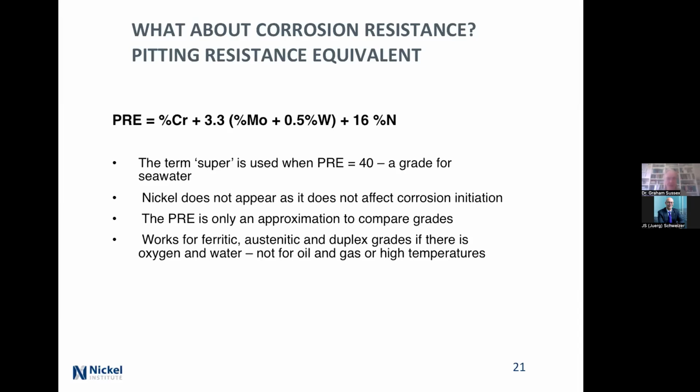This thing was originally worked out for austenitics, but it actually works quite well for ferritics and duplex grades as well. But do remember, it's put together for oxygenated, chloride-rich environments. It doesn't work if you're talking about oil or gas, and it doesn't work if you're talking about high temperatures, where you simply want a good film on the surface, good oxide film on the surface.